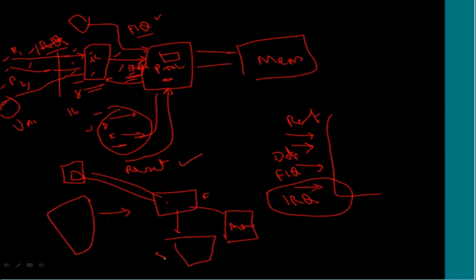The first level is only to do the minimum work required as soon as the interrupt is generated. When IRQ is generated, and the ARM processor gets time, because there is no FIQ or data abort or reset pending, it will come and service this interrupt. In the first level handling, it will do what is minimum required to satisfy the device. That means if something has to be read from the device and put into memory, it will do that, or it has to inform the device to continue with the next thing, and then it will defer further processing to the second level of interrupt handling.